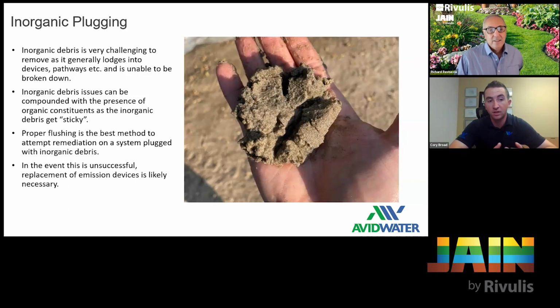One thing that's important to note is inorganic debris can be compounded with the presence of organics. Organics tend to get sticky, they're living, they're films, they're these microbes that we've talked about. And so they get sticky, they grab a piece of sand or silt or clay that otherwise would have gone by. And now that's gotten stuck. And now the next one comes by, but doesn't go, it sticks as well. And then you end up with this kind of compounding effect. Proper flushing is always the best method to attempt remediation on inorganic debris. Hopefully it's stuck on maybe the outside of the emitter.